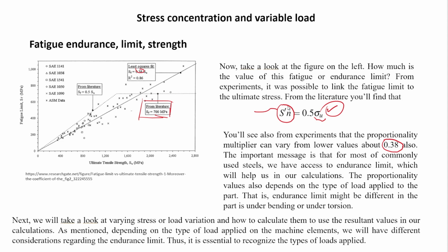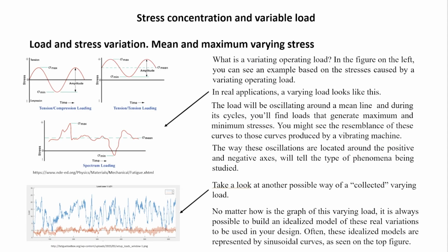The next thing to see is that we have been talking about fatigue appearing where variable load is present. But variable load, I mentioned, also has different definitions or different characteristics. And this is where these charts come very handy. The first two charts here are idealized versions of what a variable load is. You're not going to find in practical applications something close to those two top charts. They're very neat, very organized, clean. You're not going to find that.